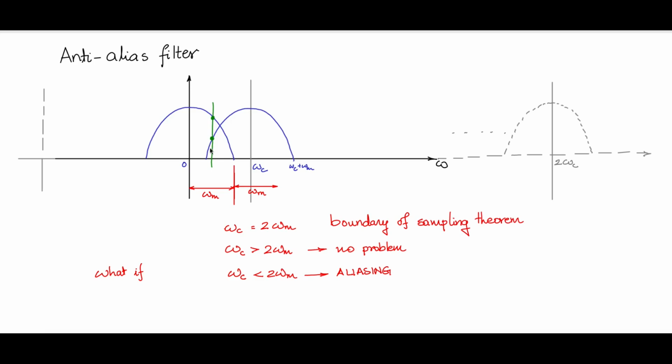Which one should one take for reconstruction? This is the dilemma, and it is a problem you will not be able to resolve. You will not be able to reconstruct the original signal because of this aliasing. The information is lost. You won't know whether to take this or this. These are the alias points, and you call this an alias. Signal reconstruction in such cases is not possible, even according to the Shannon sampling theorem.